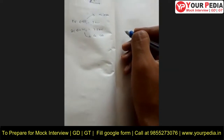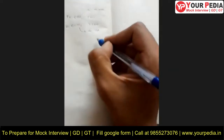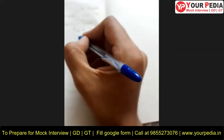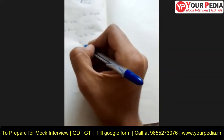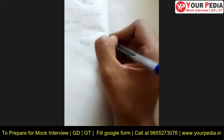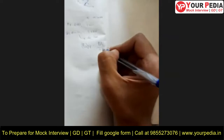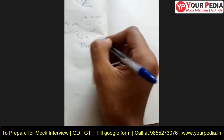And you have said that it's at 0.75, like 75% of full load. So for full load copper loss, we need wattmeter 2 reading divided by 0.75 whole squared, which will give the full load copper losses.